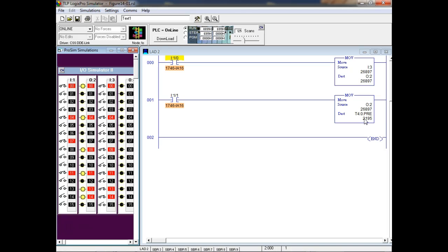I couldn't send it to an input port data file because it would be reestablished the next time it scans, and it would go back to whatever the input port says. But I can definitely send this to an output port. Like say if you turn off input 1 and all the outputs go off, you would have to do that. You could use a single input, but you'd use a contact, and you would probably use a field, or you could use a move. Yeah, I could.